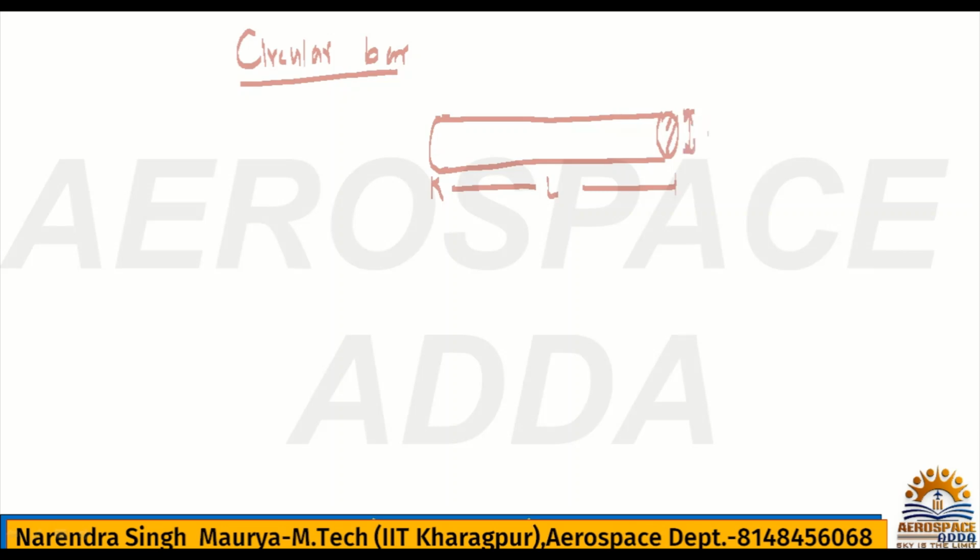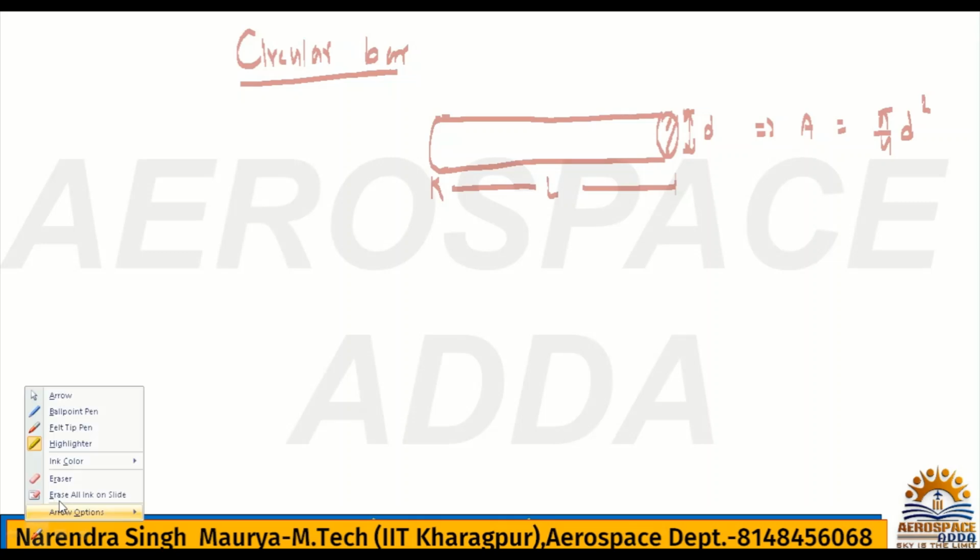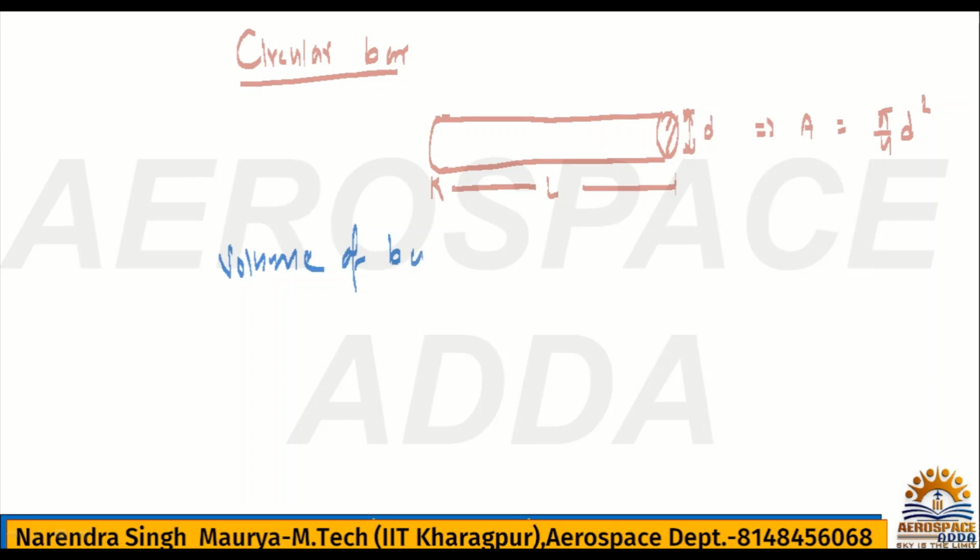What is the diameter? Small d. If I say what is the area, you have to say pi by 4 d square. Now if I say what is the volume of the bar, because we are interested in volumetric strain, so what is the volume of bar V? It is nothing but area into length. So pi by 4 d square into length.